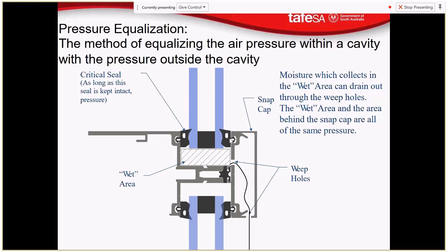So when that seal is compromised, then water makes its way down into here. And that's why we have weep holes where the water can flow out into that exterior capping on the pressure plate. And then that has weep holes in that so the water can flow out of there. So even when this rubber deteriorates on the outside, we get some bits of water, it's all directed outside once again. This seal on the inside of the building is critical.